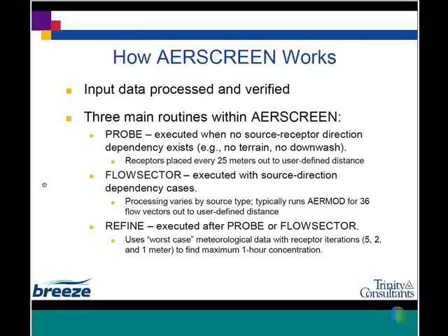So with the AERSCREEN model itself, you put in your input data, it's processed by the executable, there are some quality assurance checks that are performed so that all of the data is verified, and then it kicks off one of 3 routines, whereas AERMOD will look at each individual source's plume compared to user-defined receptors. The AERSCREEN program is going to auto-generate receptors based on these different routines.